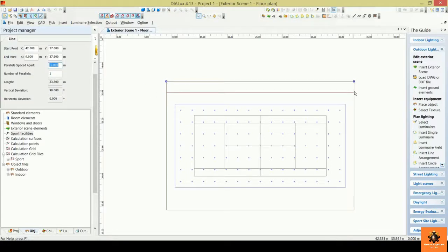That's good. This is the new line that the poles will be inserted on, and it's 2 meters away from the border line. It's minus because the new line is below the main line, not above it. We do the same thing by drawing a reference line down here from that border. We go to draw reference line and start from that point till that point, and in this case we make the offset a positive 2 meters, not negative 2 meters. This is because the new line will be above the lower line.